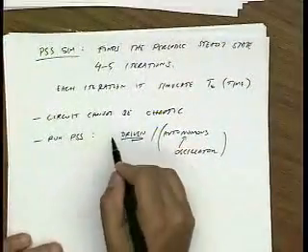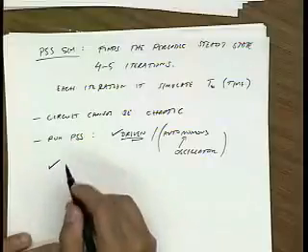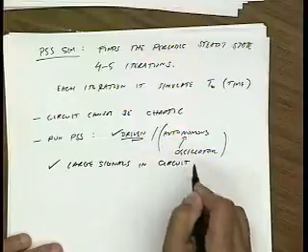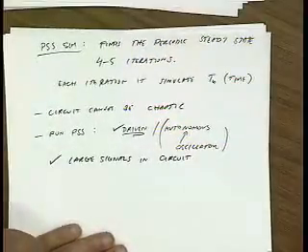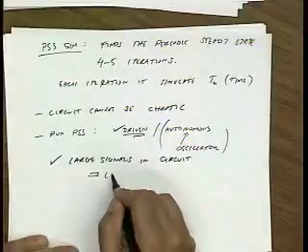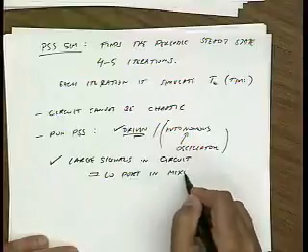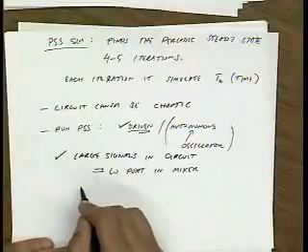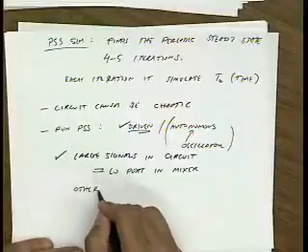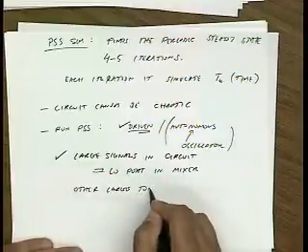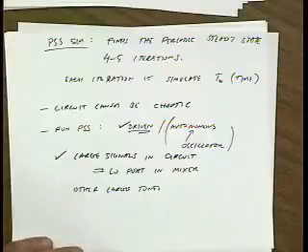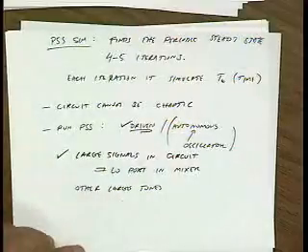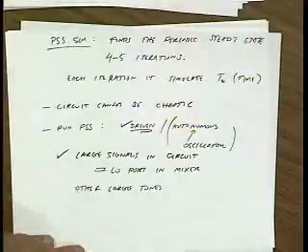The next thing we need to give, so we have to do this checkbox. The next thing we have to check off is the large signals in the circuit. Okay. So for a mixer, what are the large signals in a circuit? The LO port. There are situations where you want to put in 2 tones or 3 large tones. Then you could also put in other large tones. For instance, as we'll see, if you want to do a true IM3 simulation in a mixer, you would actually need to specify at least 2 large tones. Turns out that with small tones you can get away with it, but we'll come back to that.